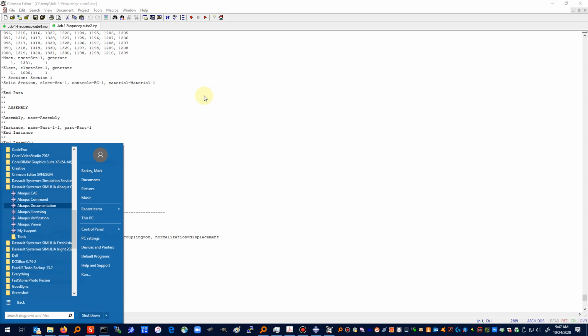Instead of using a mesh seed of 0.2 or 2 or whatever we used, we can change our mesh seed. It has all these optional parameters. So this is a required parameter. Set this parameter equal to the label that will be used to refer to the section control definition. All section control names in the same input file must be unique. So they have all these different things: distortion control, drill stiffness, element conversion, element deletion, Hourglass. Okay, this is one we used.